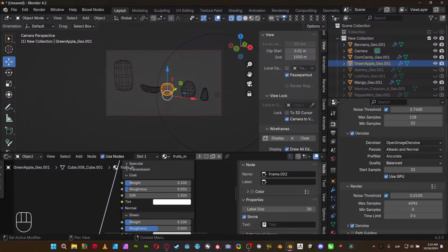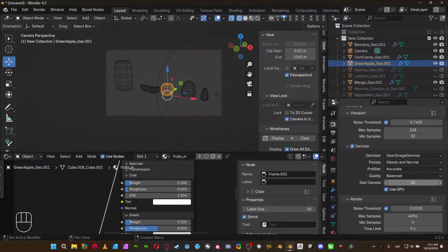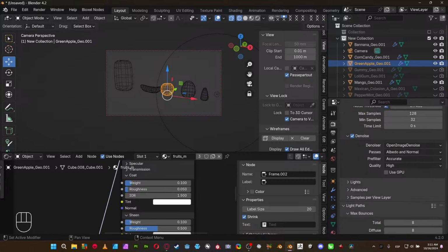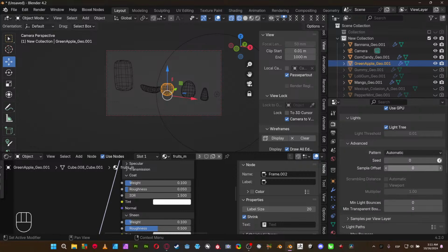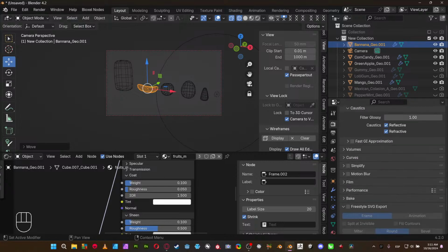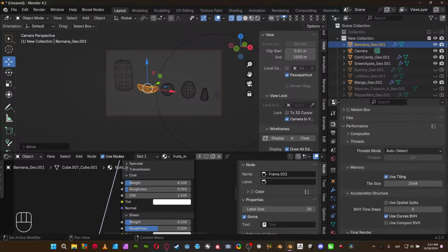Let's just make a render. I'm gonna use the GPU in order to avoid having you waiting in there. I'm gonna put some basic settings in there. I will not use anything fancy. Let's just click these guys because I need minimum bounces in there, like 4 as a minimum, just to bounce the light in refractions for this guy. Yeah, and performance, I'm gonna use 256, and let's just hit the render.